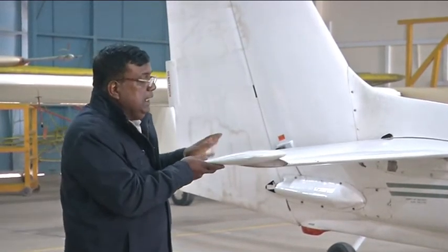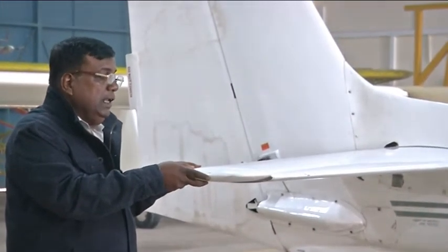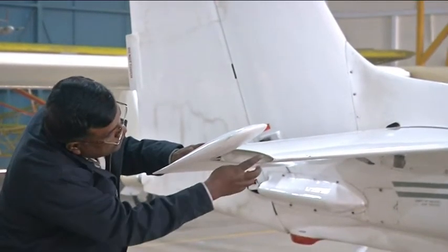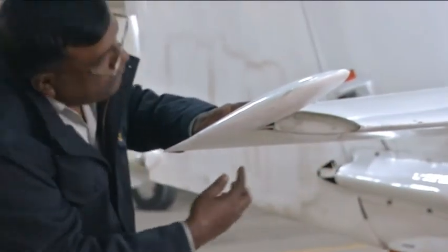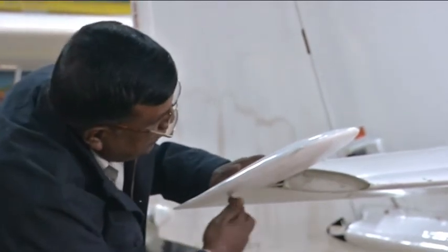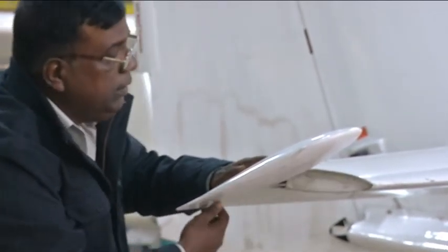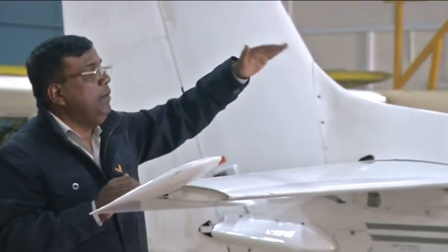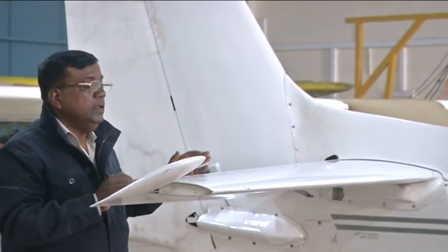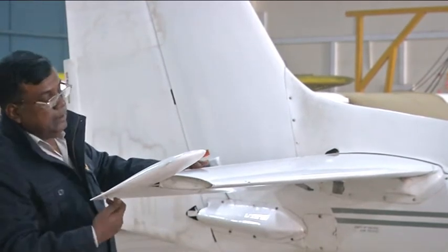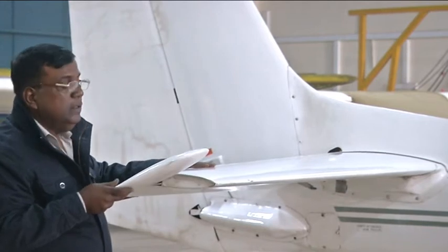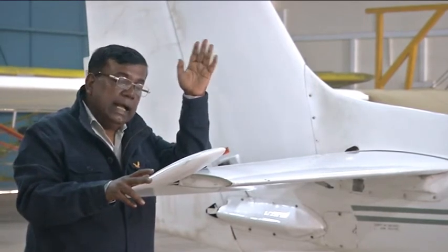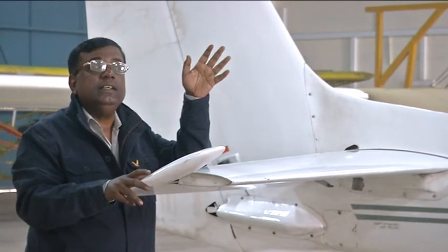Let us understand what CL delta E is, what it means. Remember, if the elevator positive angle is deflecting downward like this, as it goes downward, this takes a shape like this, and it is almost as if it has changed the camber of this symmetric aerofoil. Because of that there is additional lift. Because of this change in the camber, or because of the change in elevator deflection from zero to some positive value, there is an additional lift, and that additional lift per unit elevator deflection is called CL delta E.